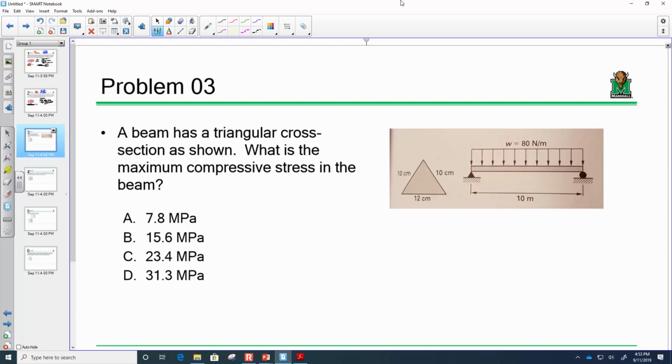And we did that in concrete and steel and you name it. The last one, for shear, transverse shear stress, is VQ over IB. That's your fourth fundamental stress formula. Those are the four fundamental formulas to determine stresses in skeletal structures. The whole point of mechanics of materials is to determine what those fundamental stresses are, and then what happens if you have multiple stresses combined together.